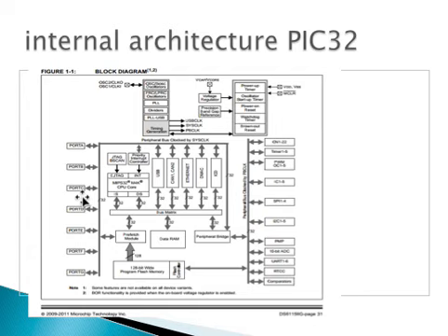So it's got in here, for example, port A. So you can use port A, port B, port C, port D, port E, port F, and so on. So as you can see, these are ports. What you do is identify which port you want to write to and which bit. Normally the ports could be about 8 bits. So you can identify any bit within the port and either write to it or read from it.